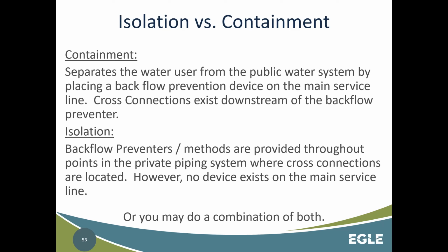When you put that on there, if any type of backflow event occurs and it triggers that assembly or device, it prevents the contamination of the public water supply, right? That is considered contained because whatever happened is contained to that building, right? But that's not necessarily great because that means everyone within that building is exposed to whatever the health hazard is that's in the water now, right? That's containment.